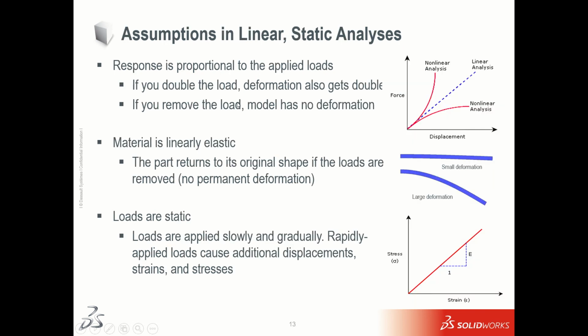And there are three assumptions in static analysis. First one is that the response is proportional to the applied load, meaning if you get any deformation for a particular load and you double that force, then the deformation also doubles, so the linear assumption is there. Then the material will be elastic, meaning if you remove the load, then the part returns to its original shape. And the last one is that loads are static, meaning you can't apply a sudden or impact load. Here loads are applied only slowly or gradually.